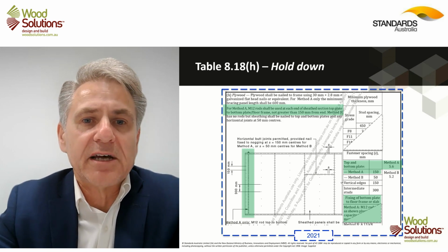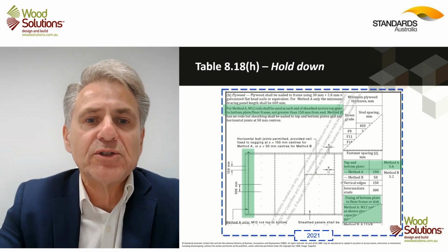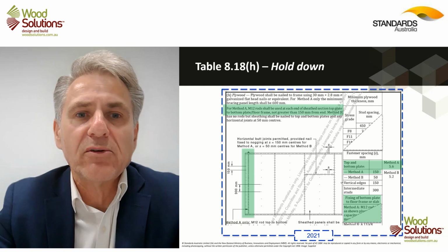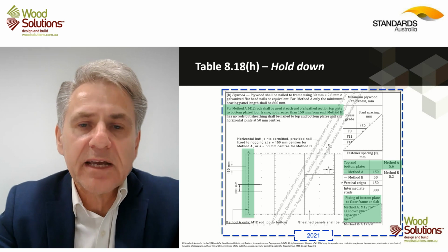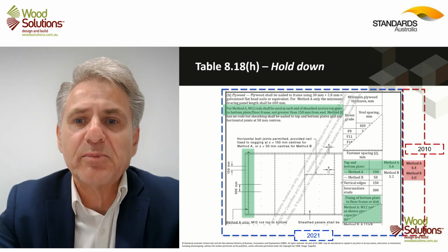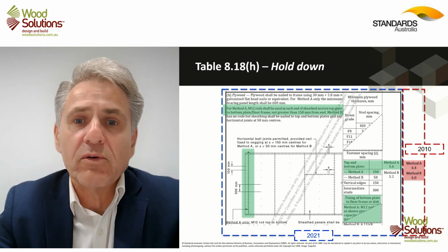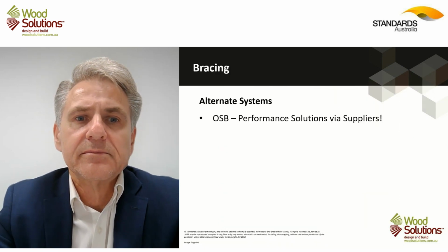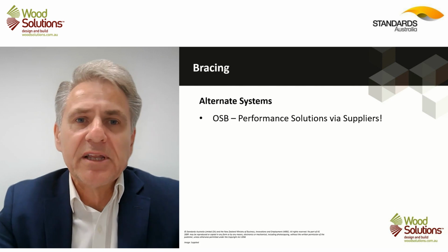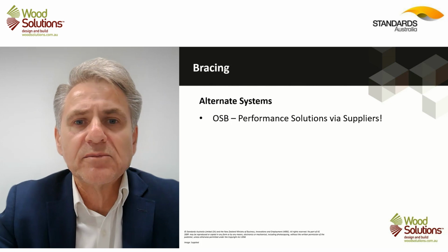So basically, if you're going to put in a double sheathed wall system, we're then introducing the vertical rods, the M12 rods, at each end of that brace wall section. And the JD5 capacities are provided. Previously, the JD4 capacities were obviously higher. So typically our brace systems are the traditional ones, but there are alternate systems that are being used in the marketplace.